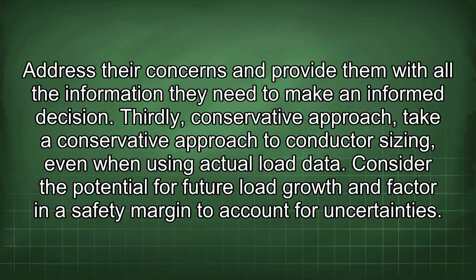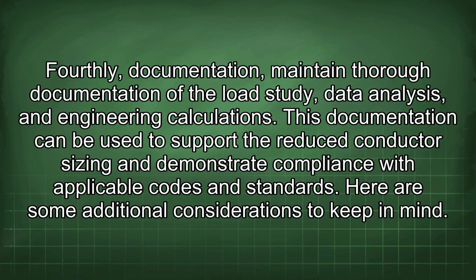Thirdly, conservative approach. Take a conservative approach to conductor sizing, even when using actual load data. Consider the potential for future load growth and factor in a safety margin to account for uncertainties. Fourthly, documentation. Maintain thorough documentation of the load study, data analysis, and engineering calculations. This documentation can be used to support the reduced conductor sizing and demonstrate compliance with applicable codes and standards.